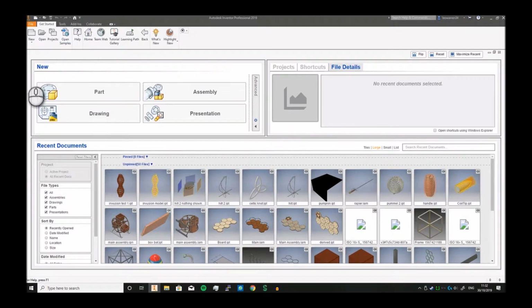And here's what we have: the selection. We have parts, assemblies, drawings, and presentations. Parts are the base units, parts go into assemblies, and then you can take both parts and assemblies and put them into drawings, and engineering drawings, and they can be sent off to manufacture. You can also send off presentations, which can basically explode, show how stuff is made, and separate it into its core components so you can actually show how it all fits together very nicely with animations.